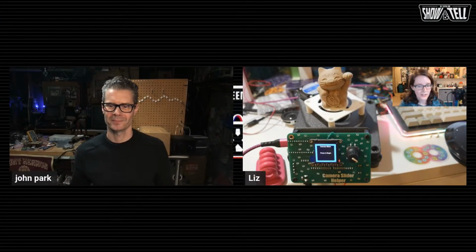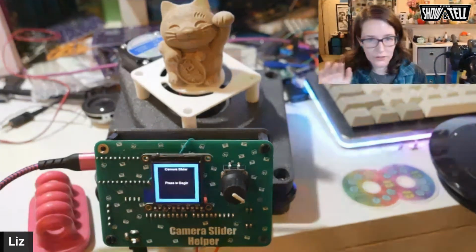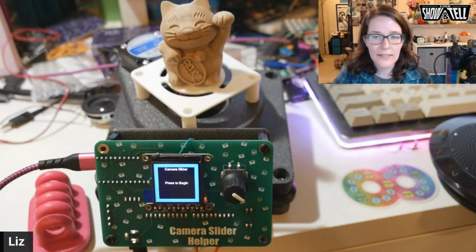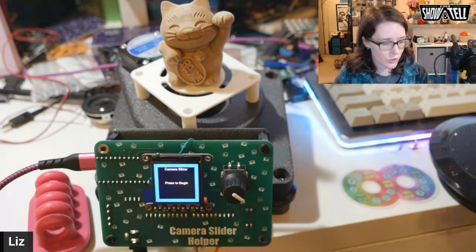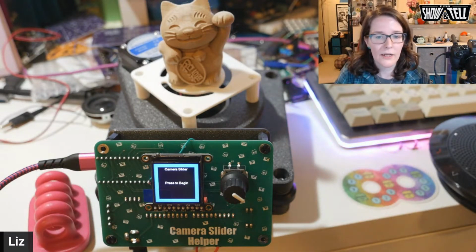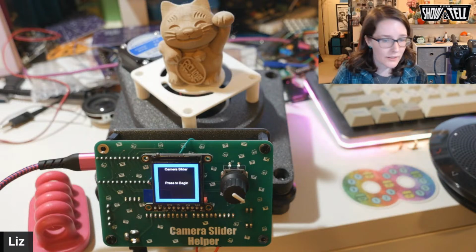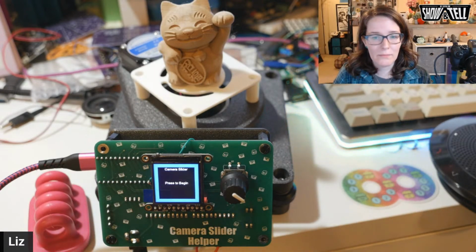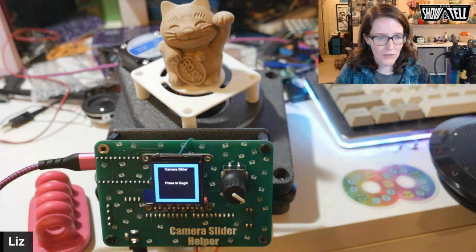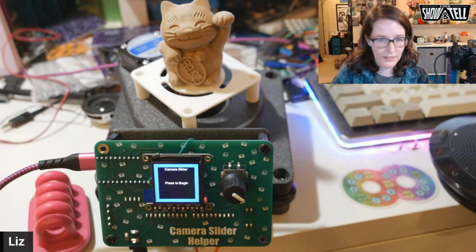Hey, so I'm working on a camera slider project with Noe. This is going to be the new version, and it's using the TMC2209 stepper motor drivers. What's really cool about those is you can use them over UART. So I have 2 of them on this helper PCB that I'm communicating with over UART with the KB2040 that's soldered to the back. By doing that, we can do things like track position and stuff like that.